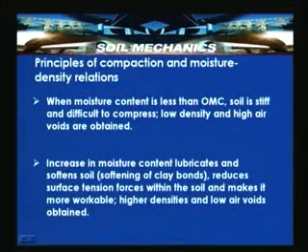When the moisture content is less than OMC, the soil is stiff. Naturally, the water is less. So the soil is stiff and difficult to compress, because the friction between the grains is very high and it is very difficult to shunt more air out of the soil mass.